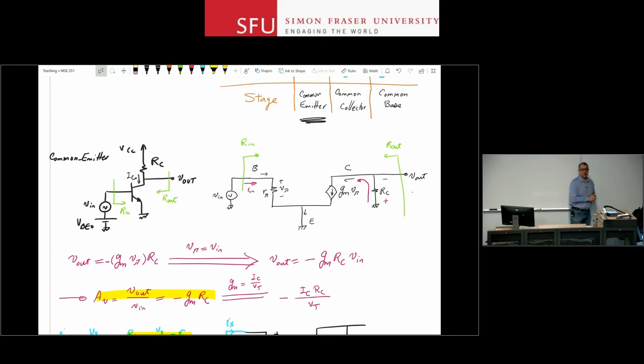And we know that's a bad idea because as soon as the temperature in the environment changes a tiny bit, you know that VT changes, you know that VBE on changes, and therefore you're going to get a hugely different current. Remember from the diode section that for every 60 millivolts of change across a diode voltage, you get a factor of 10 difference in the current.